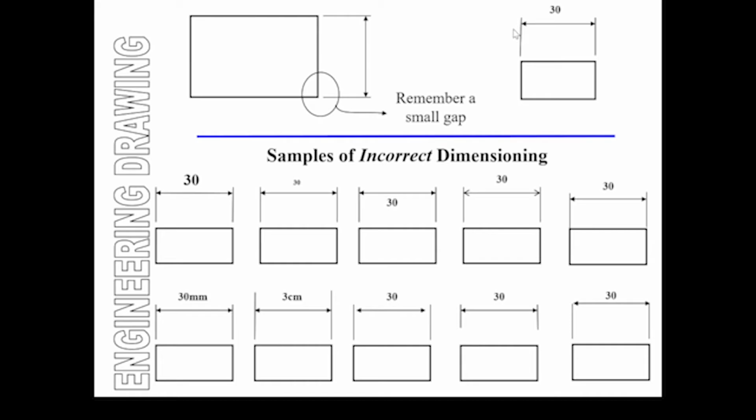That is an equilateral triangle, but as you saw in the previous image, we generally go with isosceles triangles, so long and pointy arrows. Really, that's what we need. So it's very clear from this example that the numbers are probably too large. If you think that's the reasonable dimension, then the font size here is too large, so that's what's wrong with this one.